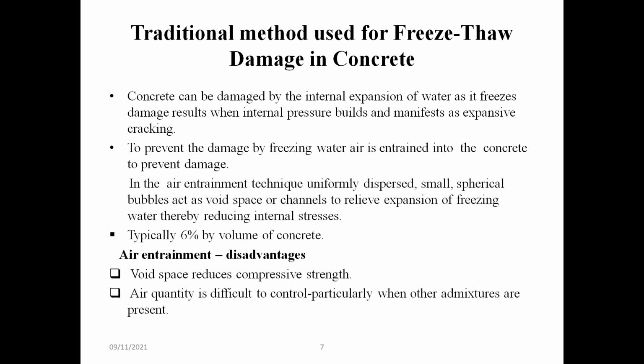Now, the air entrainment technique also has some shortcomings. As we have noted, in the air entrainment technique, air is rushed inside the concrete, into the voids of the concrete. When air is rushed in, the size of the voids may also increase. Once the void size is increased, it will lead to a reduction of compressive strength. Air quality is difficult to control, particularly when other admixtures are also present.